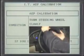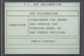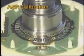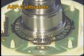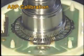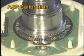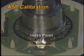After that, turn the steering wheel until a message is output. That is, when the Enter key is pressed on the scanner, it is recognized as 0 degrees. After that, the 0 point for recognizing the absolute angle by calculating the angle to the base point is set.